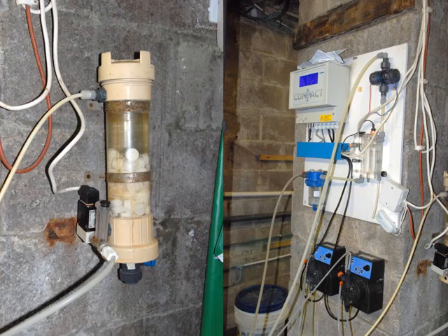In commercial spa pools, the HPA guidance states that disinfection should be automatically controlled. This means more than simply continuously dosed, and this slide shows an example from a leisure centre with a built-in spa pool. Note the use of an eroder filled with bromine tablets, or pucks, and the dosing control unit, which also controls the pH of the pool. The minimum standard for a hot tub in a holiday let or other single-use setting is an inline chemical feeder.